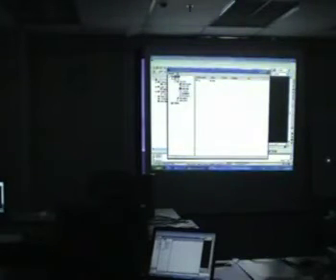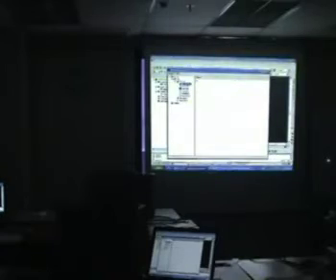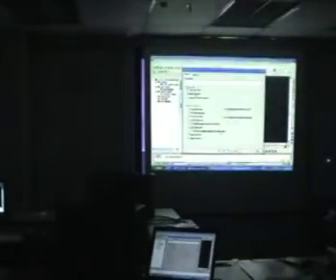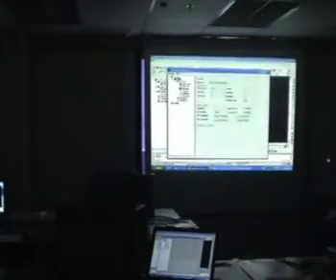So you can see there's no data here, so I'm going to add in the points. I'm just going to right click, add point group, add OGL. Okay, and I'm going to build. Running the build just means I'm running the triangulation. So we're done building surface. I'm just going to close this.